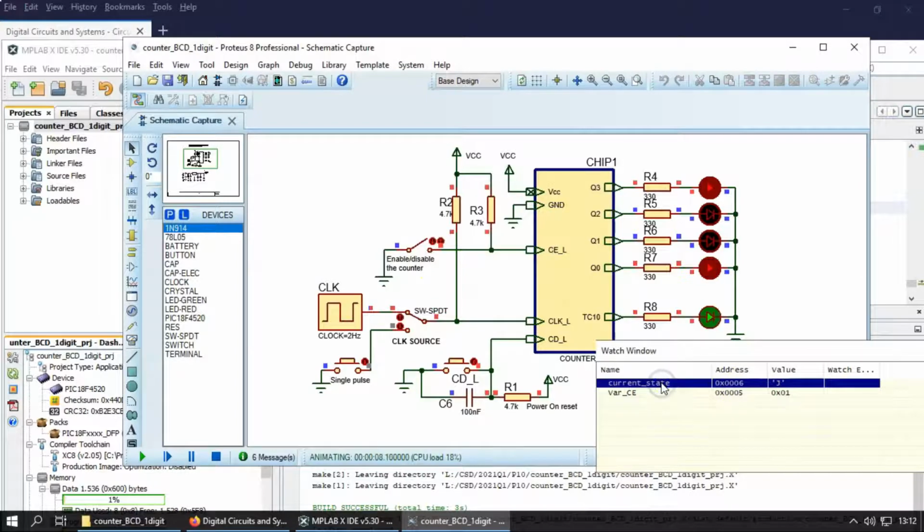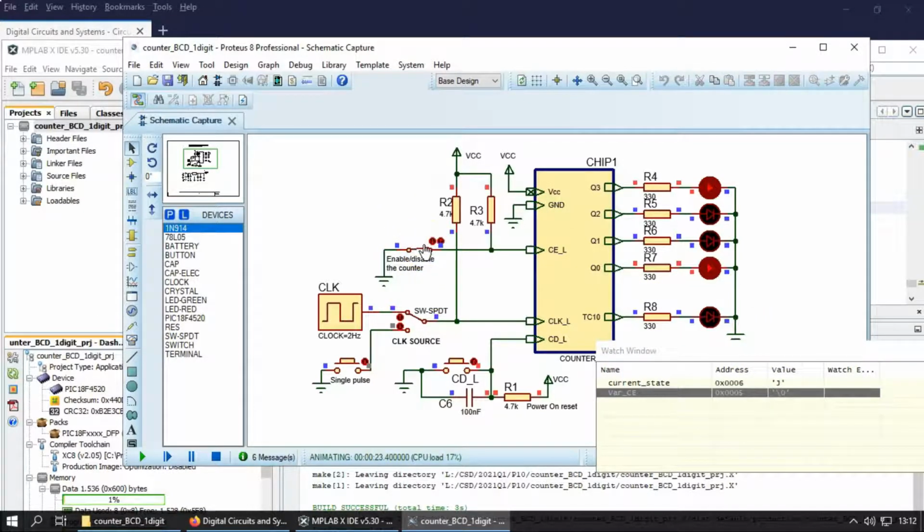You see, you have the current state that is moving every clock detected, and you see that the bar count enable is rightly detected as a 1. You see bar count enable active high as a variable, so it is 1, so you can go from one state to the next. And here you have a 0, so you keep the state like this, or the state whatever it is in which you have set. So you see, you are staying in state 2 all the time. Even if you have rising edges, you go nowhere. That's the way it works.